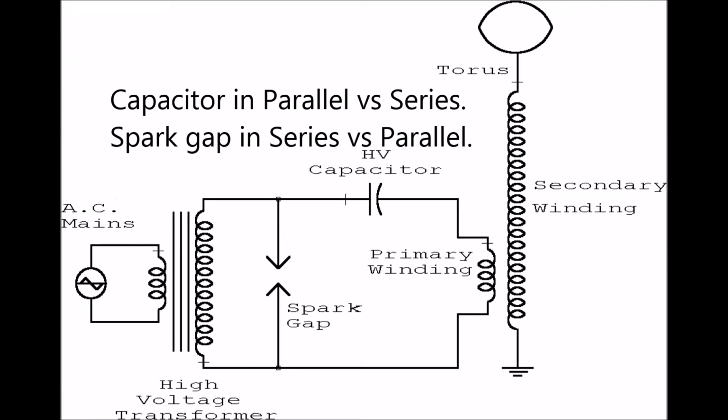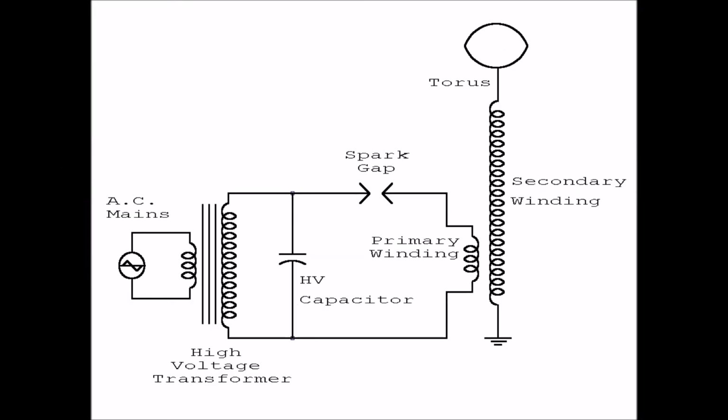See, in those two competing classic Tesla coil circuits, there is a primary coil, primary transformer winding circuit, and it's like a clapper. It gives an impulse of electromagnetic energy to the secondary because high currents accumulate in the circuit and eventually break down the spark gap, and this causes high currents that excite the secondary winding of the Tesla transformer.